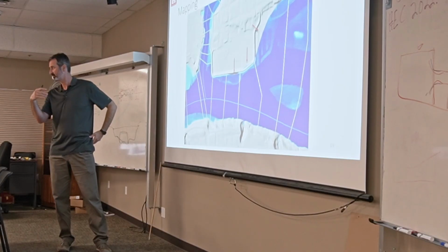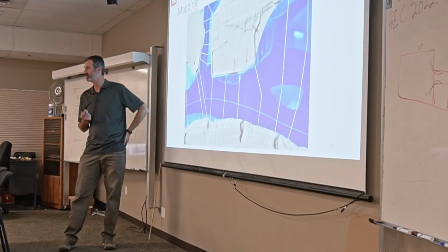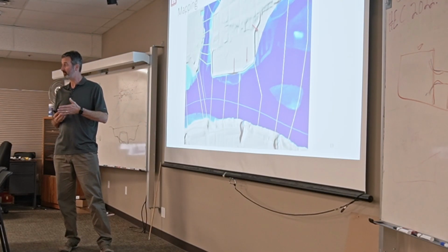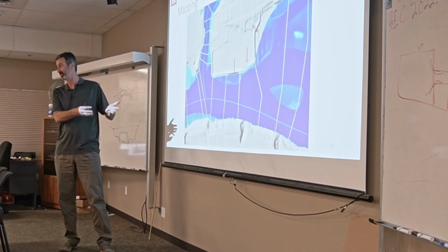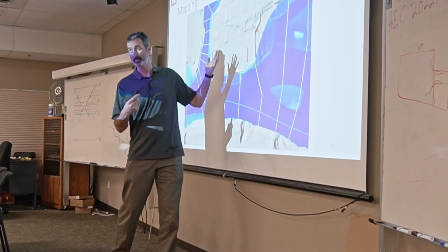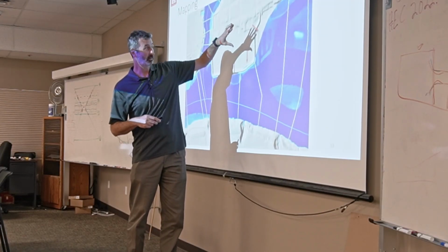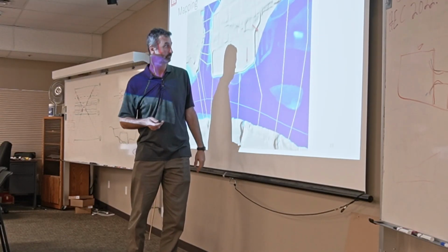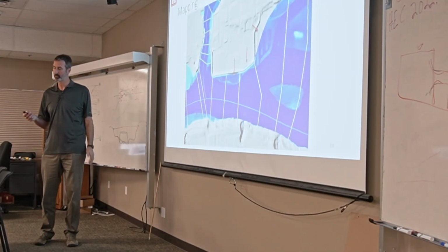Over on the right, there were other additional plot options. One of them is called something like model boundary deficiency. What we're getting at there is whether the water is being held up by an arbitrary line in your model, or by the ground that exists in the real world. If you have a big model, you might not see that, and not realize that our domain selection, not the hydraulics, is what limited the water. So look for that, and know there are other tools that help you see it.